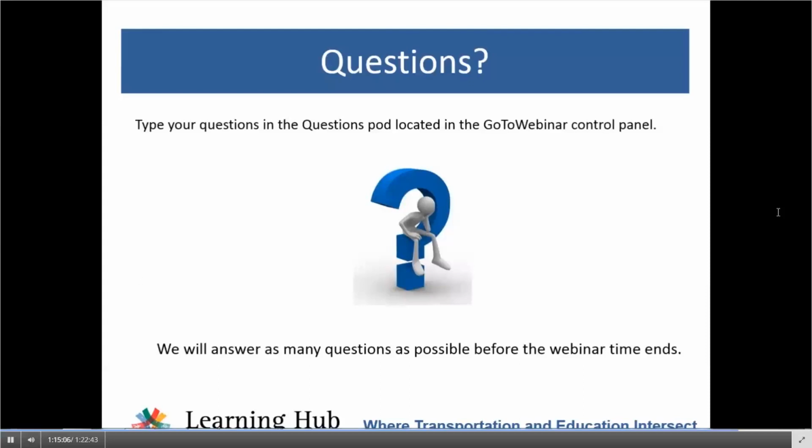you can kind of play what if with the Highway Capacity Manual by using different saturation flow rates that reflect different inter-vehicle spacings. But we don't really know for sure how it's all going to play out until I think we get a few more years down the road.